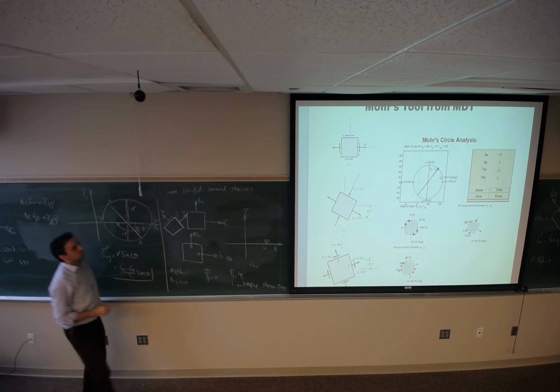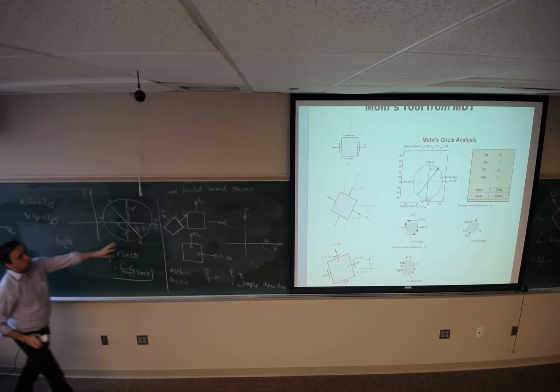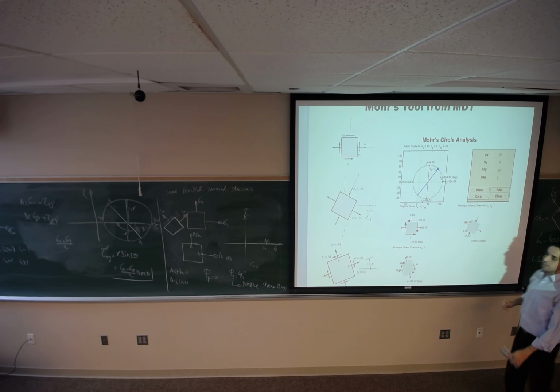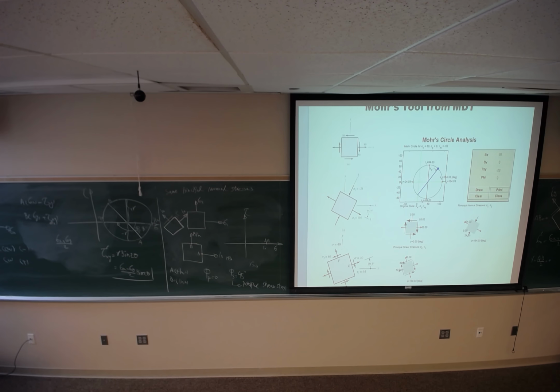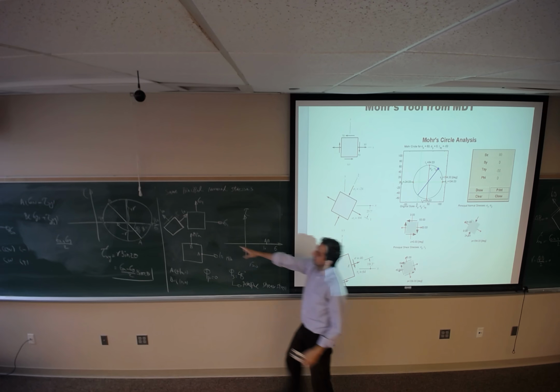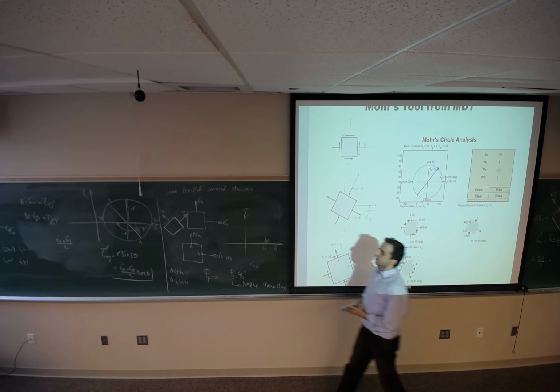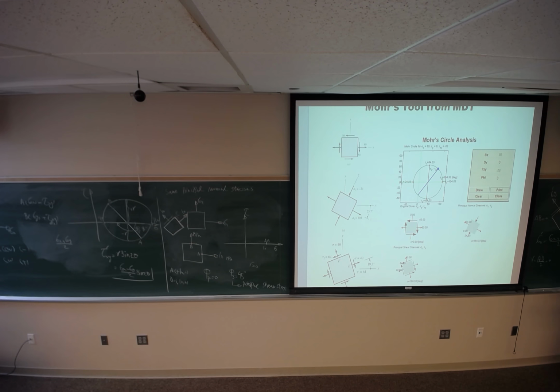So although you rotate it by the angle of 45 degrees, since we have the same value for the principal normal stresses, we don't see any shear stresses. Here we only see the same value of principal normal stresses. So this is one special case, and it's because both principal normal stresses have the same value.